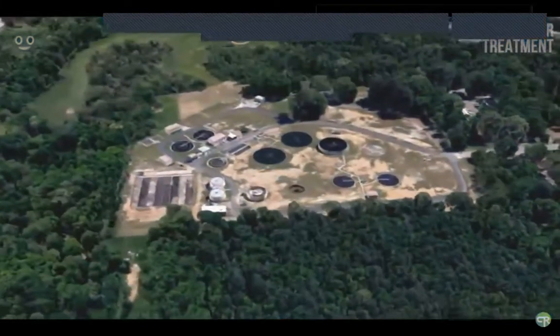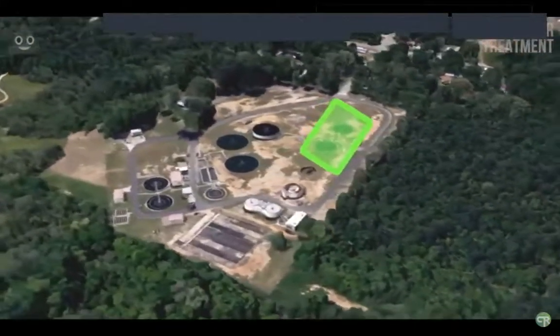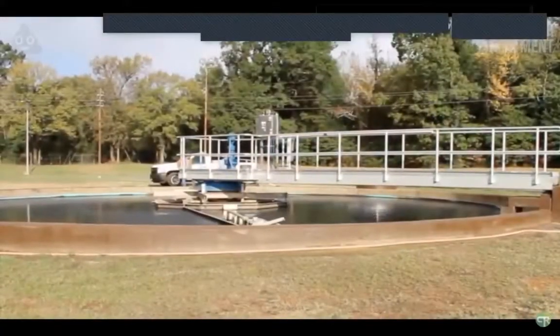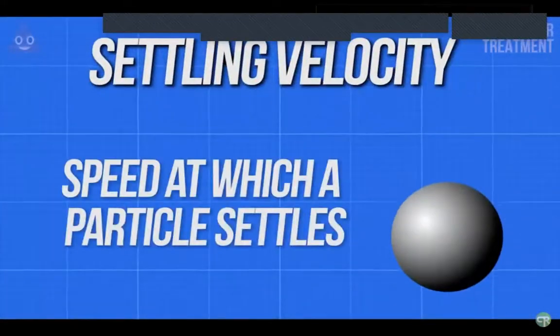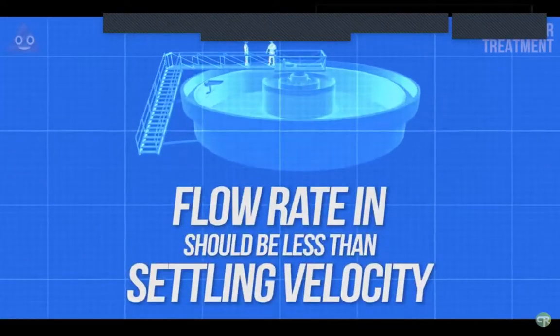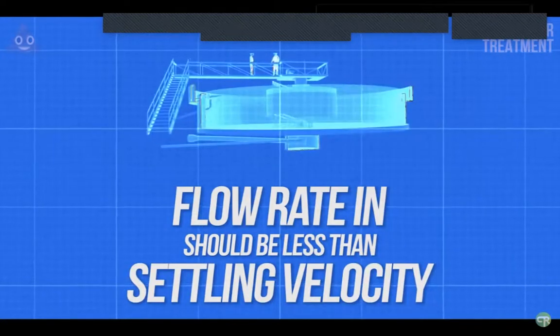Following the grit chambers, the sewage will move on to the primary treatment process, which starts with a large basin called a primary clarifier. Primary clarifiers, and clarifiers in general, function on the principle of settling velocity. This term can be defined simply as the speed at which a particle settles. For wastewater being pumped into clarifiers, it's important that the flow rate of the water being pumped in doesn't exceed the settling velocity of the particles trying to be removed.